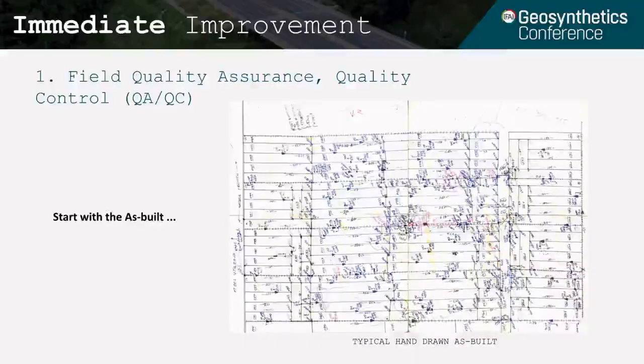An existing step in the right direction is the seldom seen GPS as-built specification requirement. Anyone with GPS equipment can shoot points at each panel intersection and grade break, and once that is completed in the field, the points file can eventually become a GPS-coordinated as-built once they're connected by a program like AutoCAD or something similar. However, to populate this GPS as-built, a reference hand drawing is likely already needed to refer back to in order to know what information goes where.